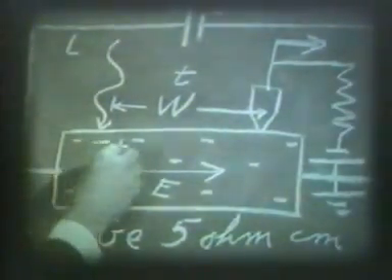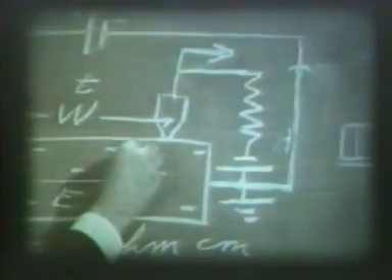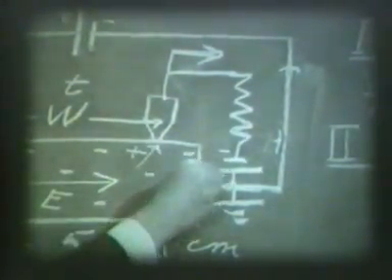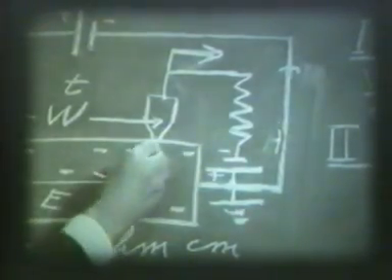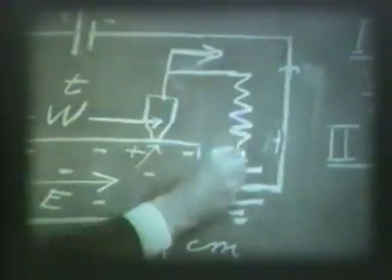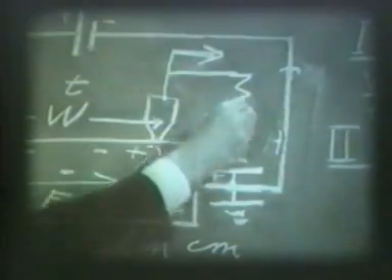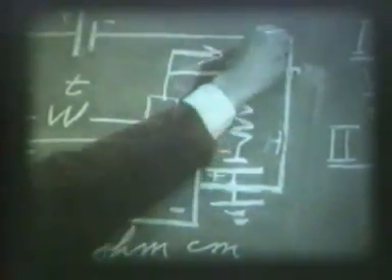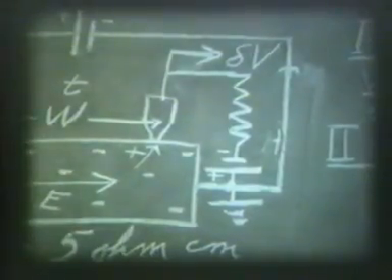If a pulse of minority holes passes under the point, the holes are attracted by the negative applied voltage. Some of these holes are collected, and their current flows momentarily in this circuit, producing a positive voltage signal, delta V, and upwards deflection on the oscilloscope. In the detector circuit, which Bill just described, we use this 22.5 volt battery to reverse bias the right-hand point.